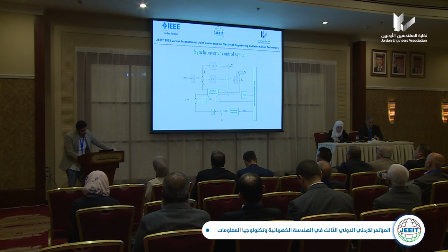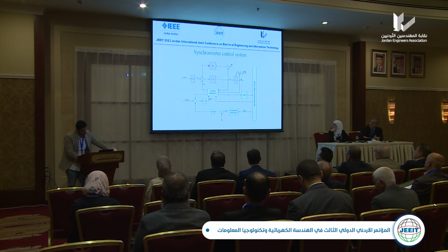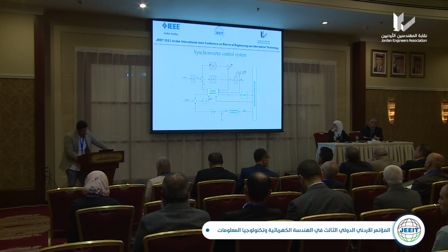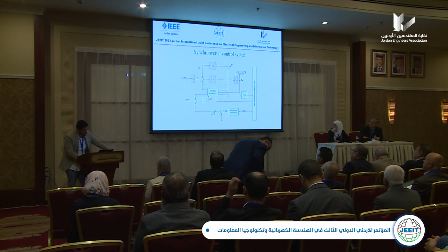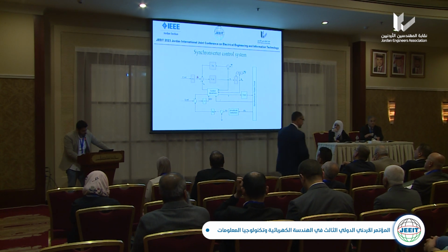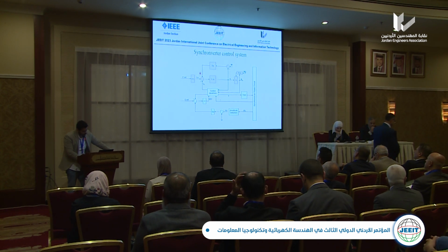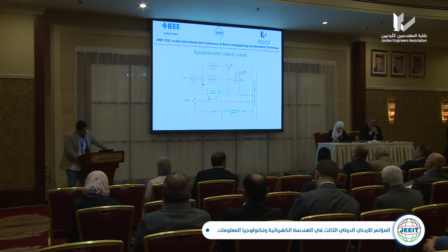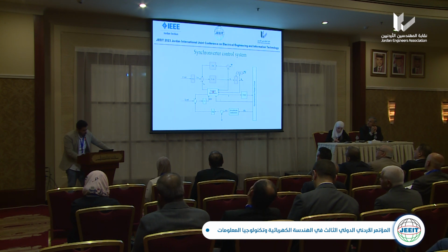In addition to this term, we have another term called dP, which is the active power group control loop. dP enters in addition to the mechanical torque, and the result of these is subtracted by the electrical torque that I'll explain later. We have it from the control equations.